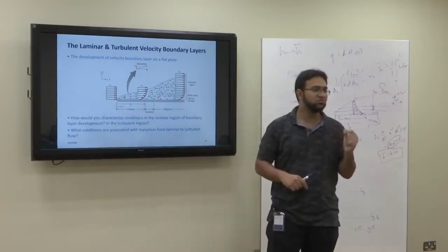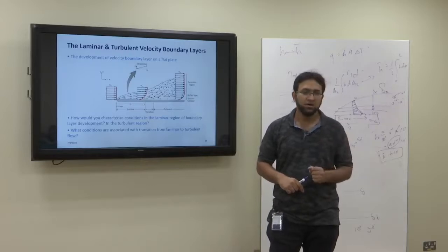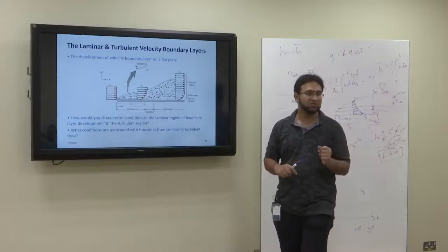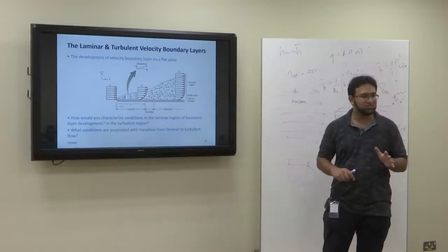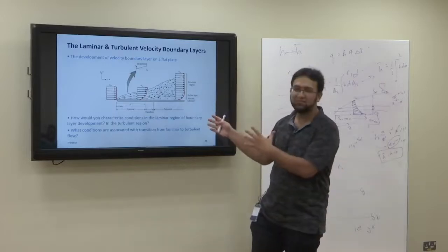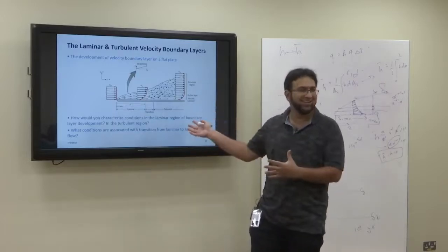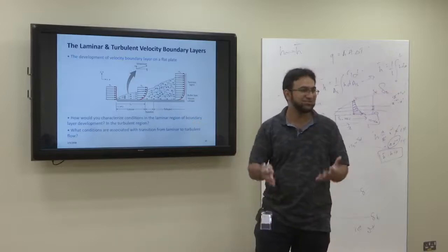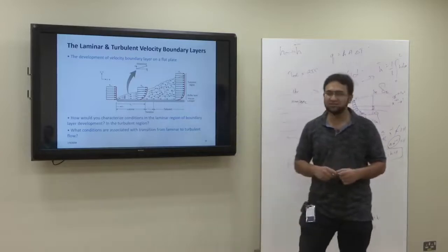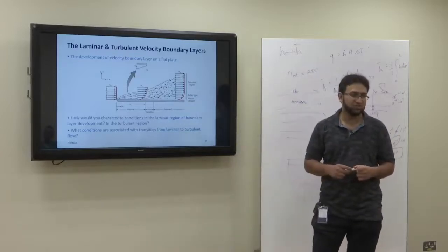Turbulence will cause the heat transfer to be very quick, and most of the time in application you want quick heat transfer. So we are most of the time interested in making things turbulent. Laminar looks good, but if its heat transfer is slow, it really doesn't help us much.